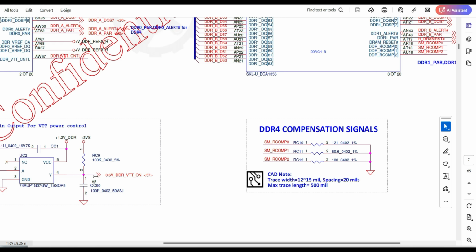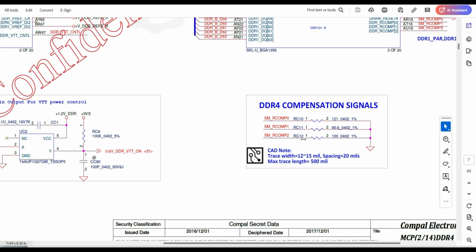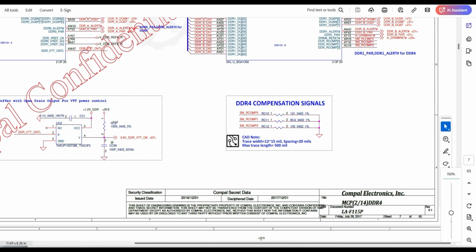Here this IC is connecting to the other IC through this pull up resistor. Here is the 3 volts, but here it should not be 3 volts because it's a complete circuit. This path is connecting to the active component. It's depending on the active component's characteristics. Here we can judge the voltage. In case this path is open, then easily we will get 3 volts here also. Okay, now understood. So this is pull down, pull up.